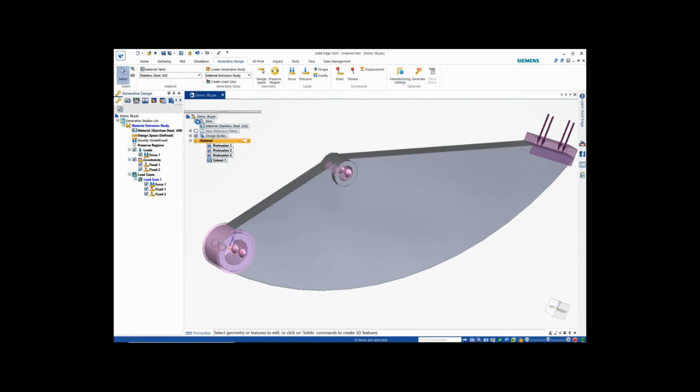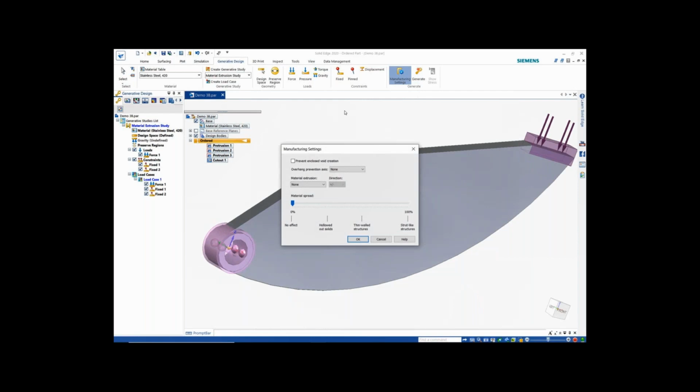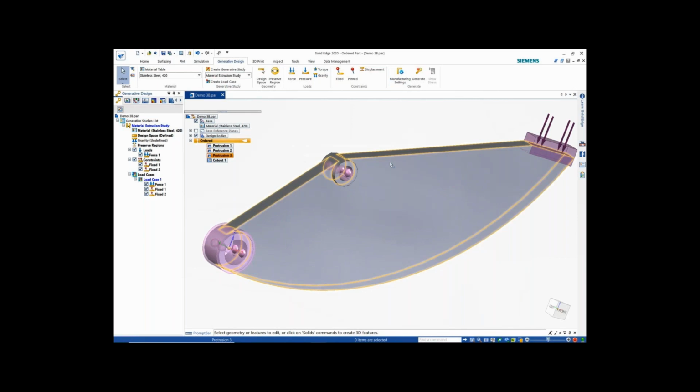So if I turn on the base coordinate system, you can see that the y axis is the axis that we want the extrude to run along. And then the overhang, also so the plus or minus is going to be kind of a symmetric type extrude, and then the overhang, we obviously don't want any overhanging material in the areas that it's going to reduce the weight.